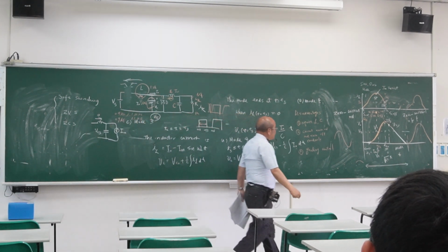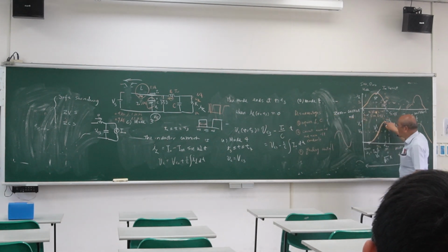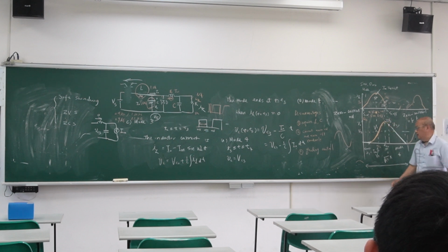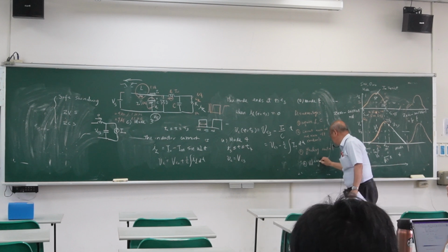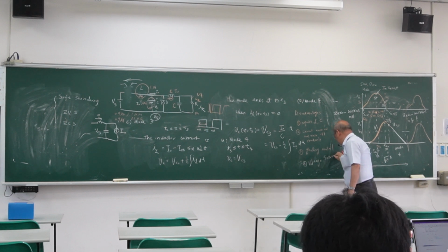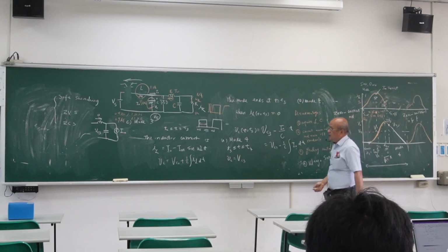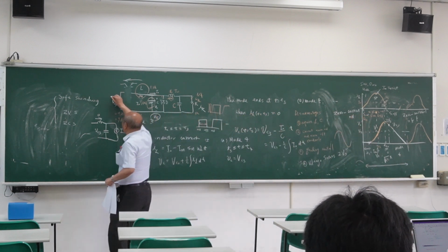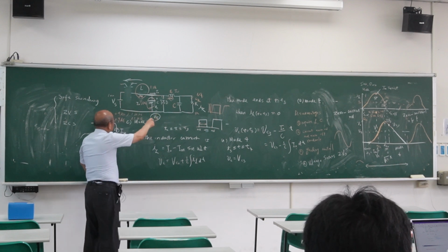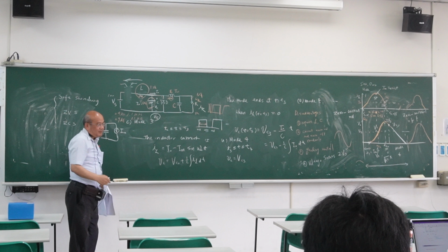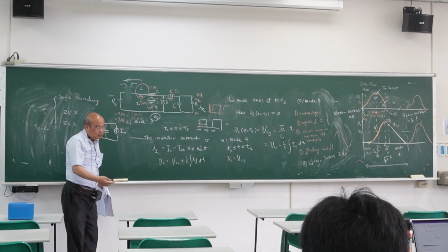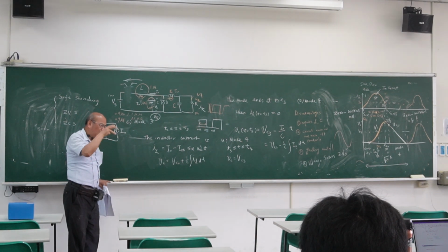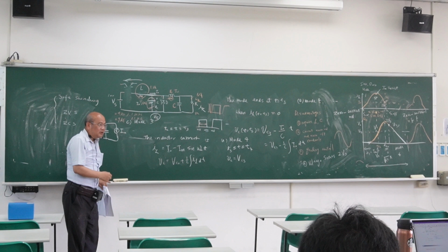But now, what is the stress for the capacitor? 2 Vs. If Vs is 100 before, you needed to choose a capacitor rated 100, but now you have to choose 200 for the voltage stress. Do you think the capacitor rated 200 is more expensive or cheaper? More expensive.